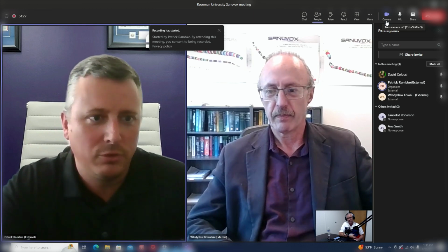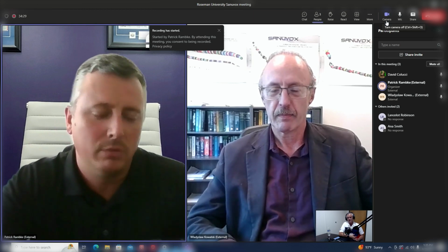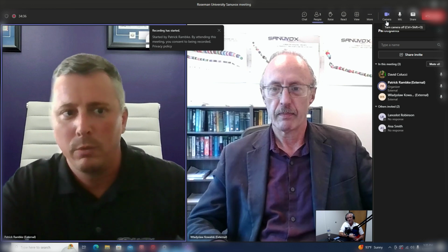Great. These are things that we definitely analyze when we talk to each individual interested party. We will look into their systems and see, because UVC has the ability to degrade softer materials. We don't deny that. And so we work with that and make sure that it's not going to do any damage to the system. So that's why we're very particular on where we choose where to place the UV. And each situation is individual. Everybody's got a different solution. So one solid answer is not really a copy and paste. So we have to see each one and size it accordingly.